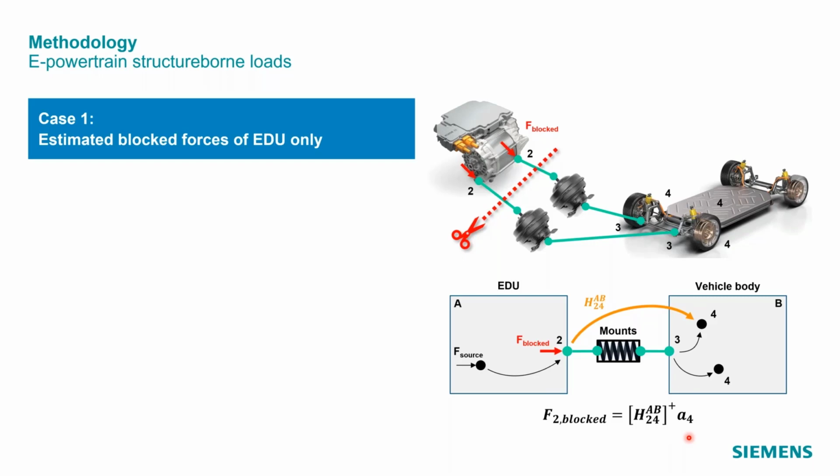In theory, this all looks good, but unfortunately, the reality is that this method probably will not yield ideal results. The simple reason is that those mounts, which in operation are meant to isolate the vibrations coming from the powertrain to the body, will also work to prevent the excitation energy from our shaker or hammer, whatever excitation source we use to measure these transfer functions. That excitation will also be dampened out before it reaches those indicators.